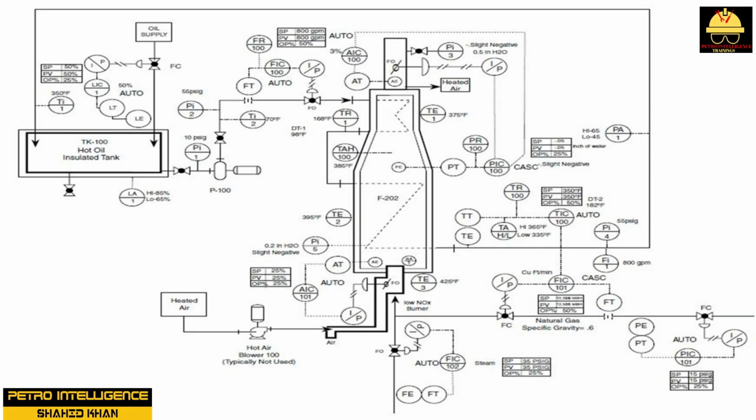1. Notify your supervisor and all concerned about startup. Downstream process technicians, I&E, engineering, maintenance, etc. 2. Ensure all safety hazards are secured. Trash, locks, old permits, etc. 3. Check equipment and instrumentation. Stroke control valves 0 to 100%, check lineups, etc. 4. Open PCV 100 to 100%. 5. Purge furnace for 15 minutes with steam.